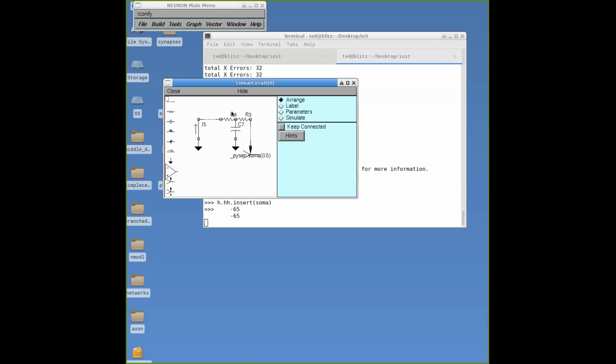So what's this business up here? This is an equivalent T circuit for the electrical properties of a glass microelectrode. This resistor, which is split in two, represents the resistance of the electrolyte that fills the electrode and whatever access resistance there is at the pore in the side of the cell where I have attached my electrode, and the capacitance of the electrode. So let me change some labels and move some labels.